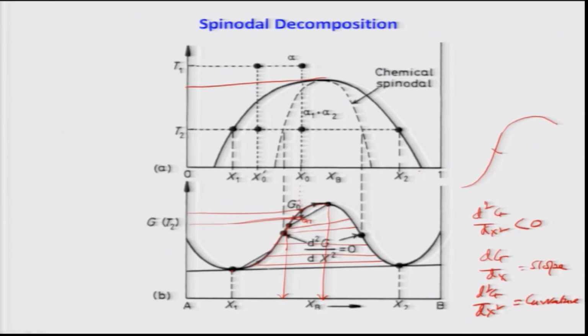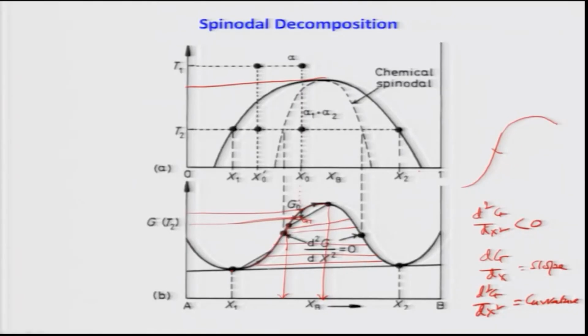So, the free energy of the system can only be lowered if nuclei of the new phases form with a composition very different from the parent phase. Therefore, outside the spinodal decomposition, transformation must proceed by nucleation and growth, and normal downhill diffusion, which I just now discussed with you, will happen. See why it is called downhill diffusion? Normally diffusion will happen down the concentration gradient.